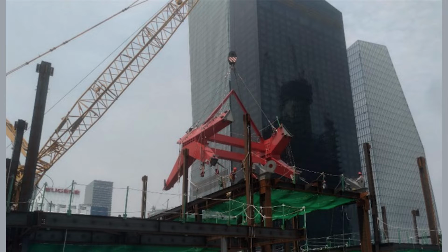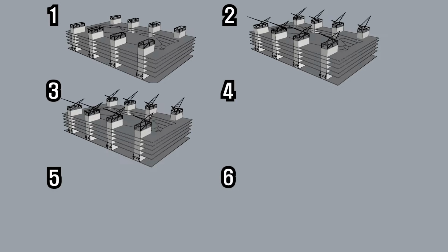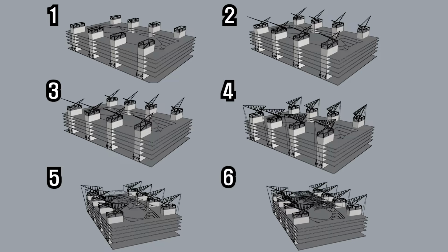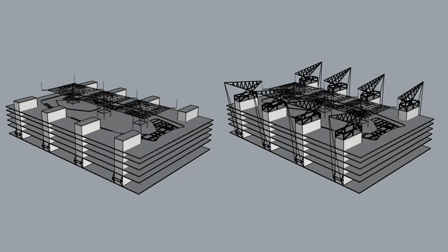Another issue during the planning was changing the sequence of the installation. According to the report written in 2010, the order of the construction was the way in which the crane structures were first constructed, and the main trusses of the kite were connected to them in the air. However, the actual construction sequence was that the kite trusses were built first using temporary band structures, and then the cranes were installed before the bands were dismantled, which is presumed to be a change in consideration of construction stability and the lifting capacity of tower cranes.